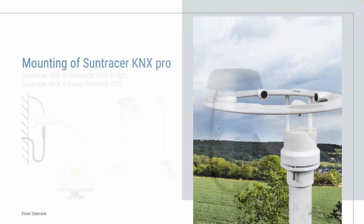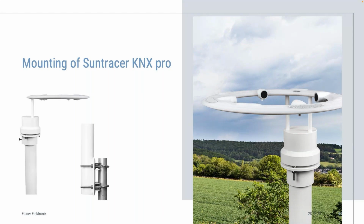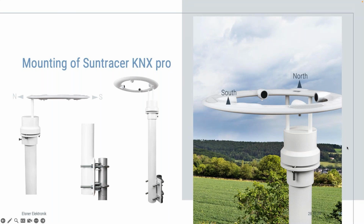Let's move on to the next model, which is the mounting of the SunTracer KNX Pro. The SunTracer KNX Pro weather station must be mounted on a mast on the building due to wind direction measurement, so as high up as possible. A mast extension as well as suitable mounting material is included in the scope of delivery. In the next photo, the total assembly with the mast extension is shown. The weather station must be oriented so that the base of the device faces north and the ring faces south, as you can see here.